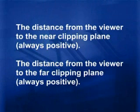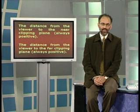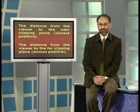The distance from the viewer to the near clipping plane, which is always positive, is specified by zNear. In order to make sense out of this discussion, please recall our discussion about the viewing frustum when we were talking about the near and the far planes. That's what we are specifying over here. The distance from the viewer to the far clipping plane, which is always positive, is given by zFar. So, making use of this very function, we can not only set or change different aspect ratio values, but we can also specify the viewing frustum.